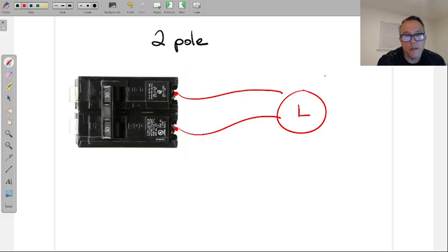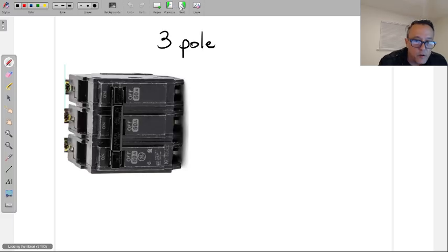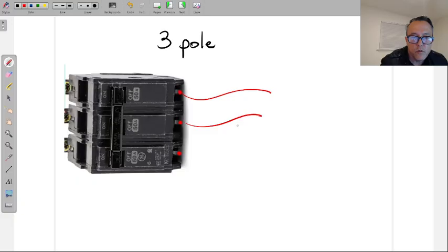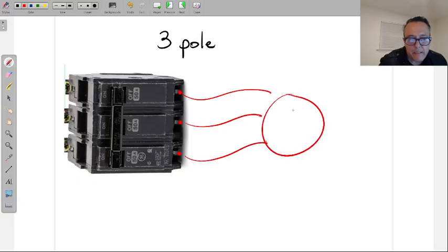Now, when you get into commercial and industrial buildings, there are 3-phase systems. And here you'll have a 3-pole breaker. This is a breaker that has 1, 2, and 3 wires leading to a load. In most cases, those loads are motors. It also could be machinery in some other way that's not using a motor. Mostly everything uses a motor, but there could be something that heats up water, or moves a crane or something like that. But usually there's a motor attached to that. So a lot of these 3-phase systems are motor loads. That's why it has a whole motor branch circuits.